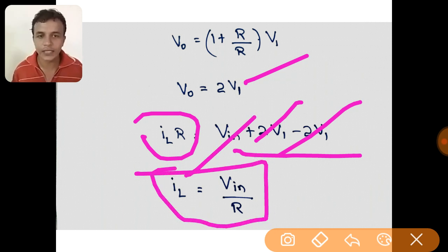So the load current that is developed is directly proportional to the input voltage that we have applied. So we are able to derive the current for the corresponding input voltage that is applied. The current that is generated here can be used for driving the circuit or driving the devices which require current. So this is a voltage controlled current source, and that current source can be used as the source for current controlling electronic devices, and this is otherwise called a transconductance amplifier. These are the other names of voltage to current converter, right?